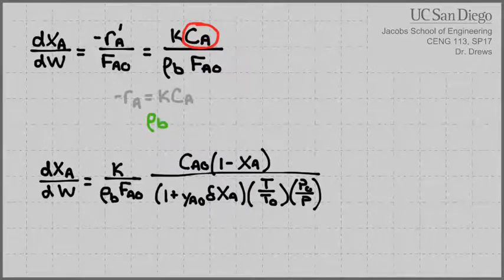A little bit of simplification can occur here, partly because by definition in our problem, this was an isothermal system. So the temperature ratio there is going to go to 1. If it wasn't an isothermal system, like the systems we're going to spend the rest of the day talking about, and probably all of Monday and maybe even Wednesday, then obviously this would need to be inside of a differential equation because there's nothing we can do about that temperature. We have to couple this with the energy balance so that we know what's happening there as well.